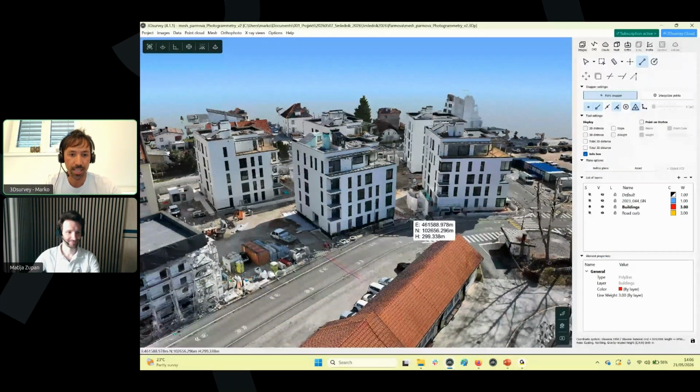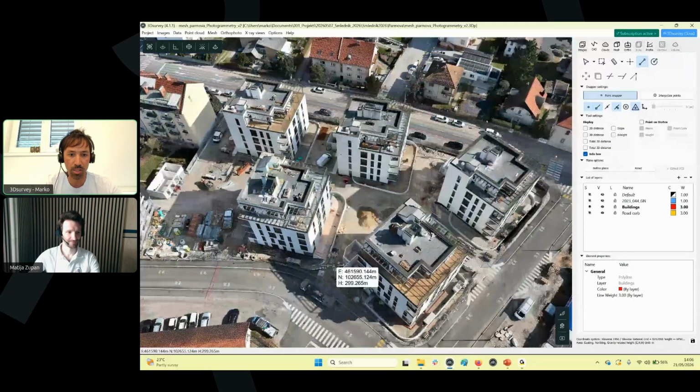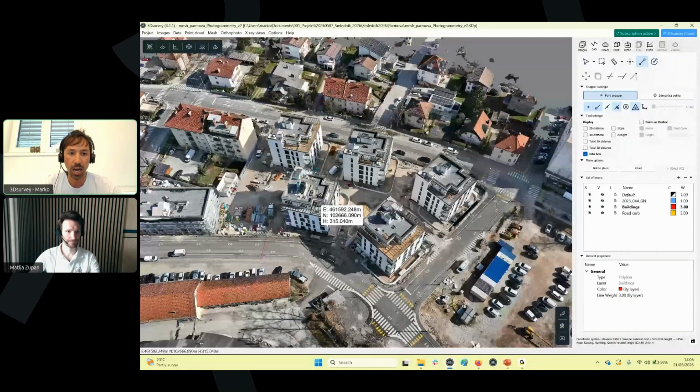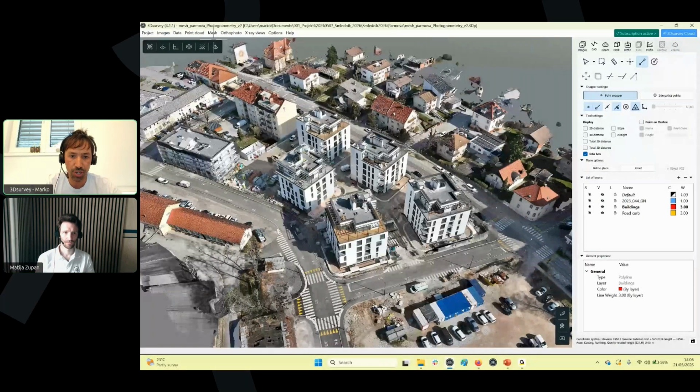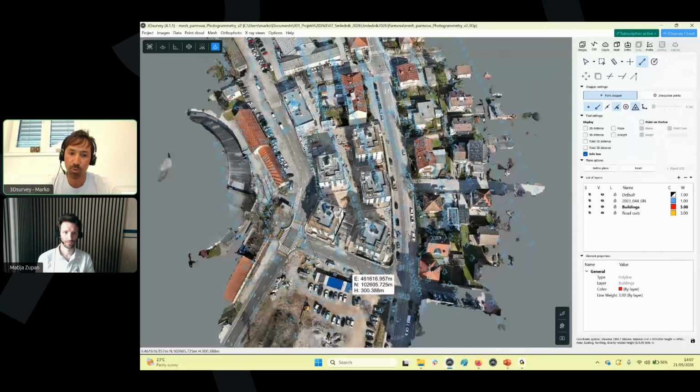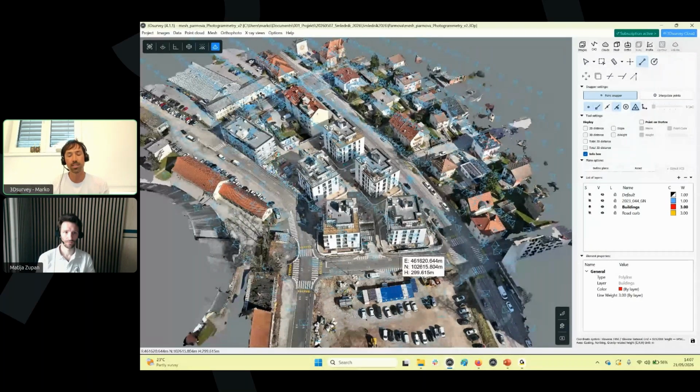Okay, very good. So here we have 5 blocks of apartments. The surveying company mapped those blocks with the help of drone mapping. I can show you also the cameras. They used the oblique mission option at the end. I think the flying height here was 40 meters. And this is really important if you're doing oblique: fly a bit lower, because when the camera is turned to 45 degrees, if you fly at 40 meters, you have probably 60, 70, or even 80 meters to the object.